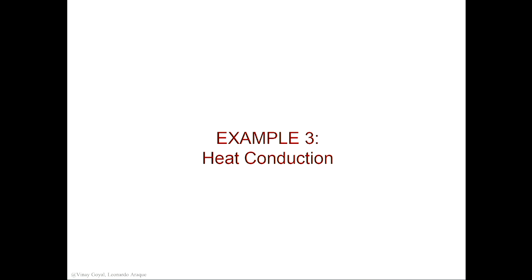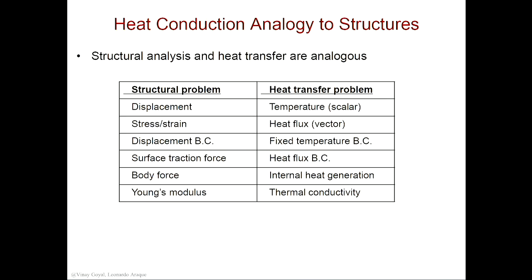So let's cover heat conduction now as example 3. Example 3 goes for many different examples. It has 3A, 3B, 3C, and so forth. So far I've shown you examples with bars, but if you want to see how this applies to heat transfer, you have displacements, typically the quantity of interest in structures. In heat transfer, you have temperature. The quantity of interest in structures is stress or strain, and then here in heat transfer it is heat flux.